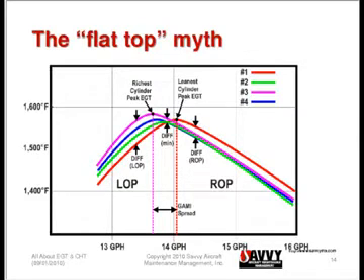Here's a simplified drawing of a 4-cylinder engine and the EGT curves for different cylinders. Once we go through this, I'll show you some data from a real engine that's just a little bit messier, but I'm starting off with this simplified drawing. It's a 4-cylinder engine just to keep the diagram from being cluttered. And you'll notice that the difference between EGTs varies depending on what the mixture is. It tends to be smallest when we're operating close to the peak EGT region, which is probably not where we want to be.